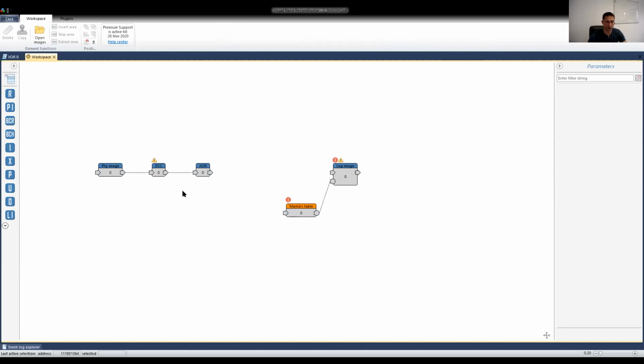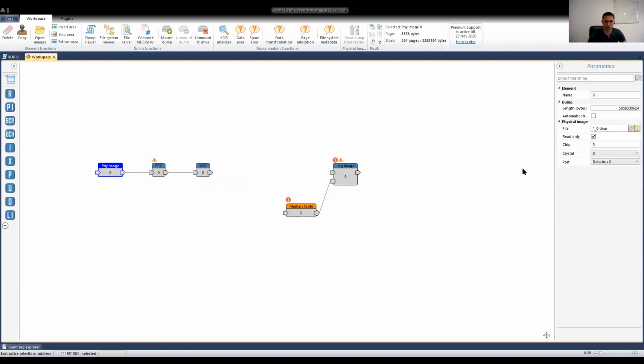And you need to adjust it, because if multiplane page allocation was used, we can't know that from the configuration. So we place the physical block size in the configuration, and you may have to change it. How can you detect it? Very easy. You just open the bitmap and look for these borders. And by the way, the highlight blocks option will take the block size which is actual at this moment, and you can just check if it's correct or not.